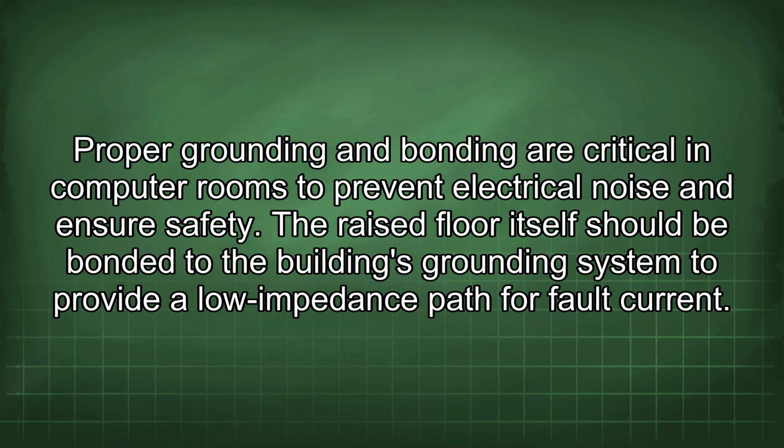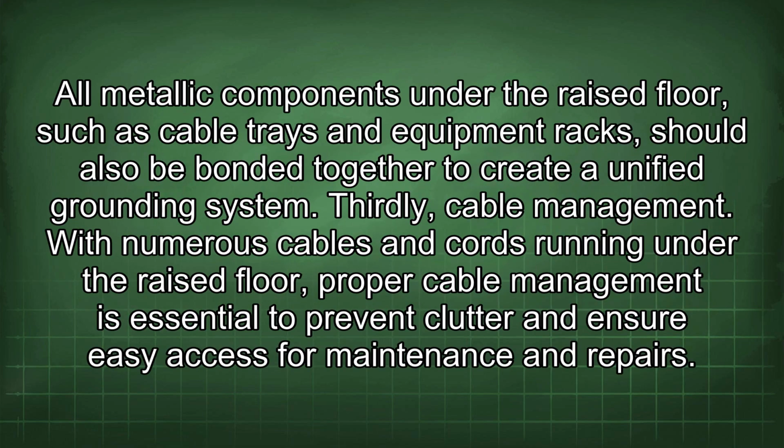Secondly, grounding and bonding. Proper grounding and bonding are critical in computer rooms to prevent electrical noise and ensure safety. The raised floor itself should be bonded to the building's grounding system to provide a low impedance path for fault current. All metallic components under the raised floor, such as cable trays and equipment racks, should also be bonded together to create a unified grounding system.